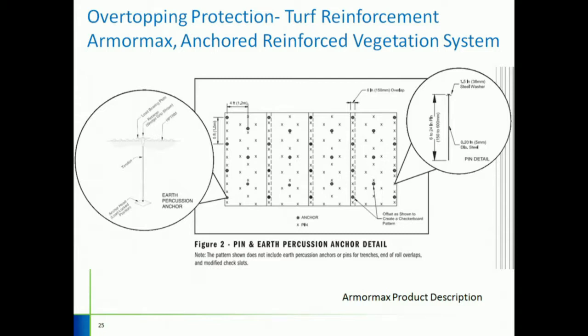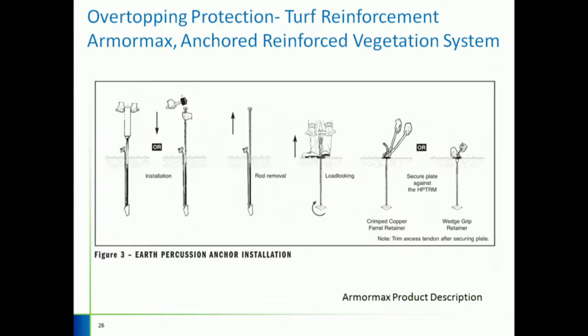Here's how the earth percussion anchor is installed. You just vibrate it down or hammer it down, and then remove the rod, turn it around, load lock it, and clip the cable, and it's installed.